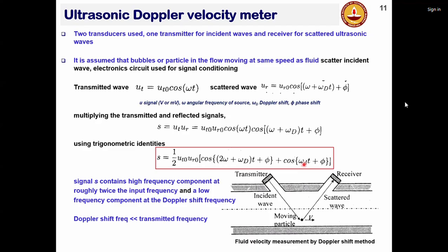Sir, I have a query. Whatever impurity or external particle is being injected in the flow, we are assuming that the velocity of the particle will be along the flow and almost similar, right, sir? Yes. But the particle will have some inertia, some finite mass. If the flow velocity is very low and the particle mass is a little higher, will that not make the measurement erroneous?